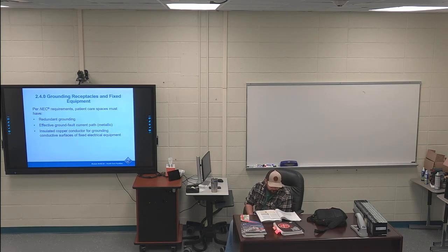On page 15, the second paragraph on the page. You have a bullet point, first paragraph, second paragraph. The first sentence is highlighted. Equal potential grounding is one method of grounding used for sensitive equipment. That's the first highlight. The rest of the paragraph is a separate highlight. An equal potential ground plane is a mass of conducting material that, when bonded together, provides a low impedance to current flow over a wide range of frequencies. So low impedance to current flow over a wide range of frequencies. That's your highlights for that.